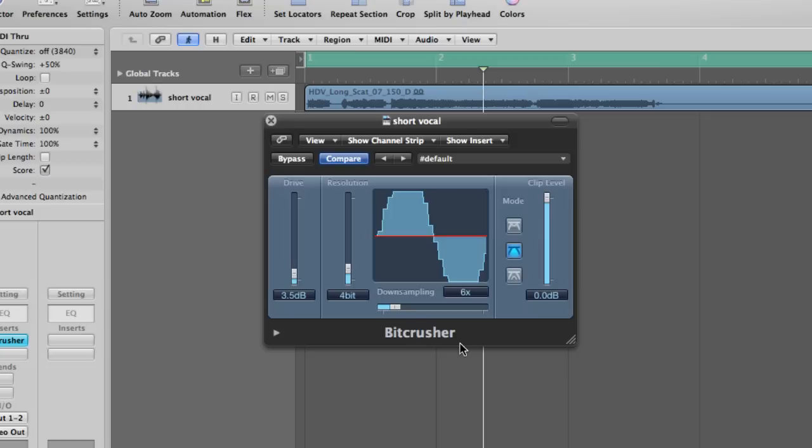Right, moving on, let's talk about the mode buttons. If you have the clip level set at 0 dB, then it will be hard to hear a huge amount of difference in the different modes. But if you start moving it down a good bit, then the difference is much more noticeable. Each mode affects different parts of the signal chain when the clip level is exceeded. So that's why when you bring the clip slider down, more of the signal is exceeding the threshold and therefore more signal is being affected by the attributes of the mode selected.